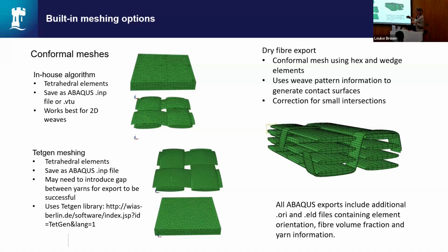But the problem comes when you've got that domain, that's typically what's filled with resin. That's part of the material, and you have to mesh that as well. Particularly if you're meshing a textile that's been compacted, you've got weird and wonderful shapes, and you get these really thin, sliver-like pockets. It's a perennial problem of how you deal with that, how you mesh that without going into really, really fine meshes or things that intersect.